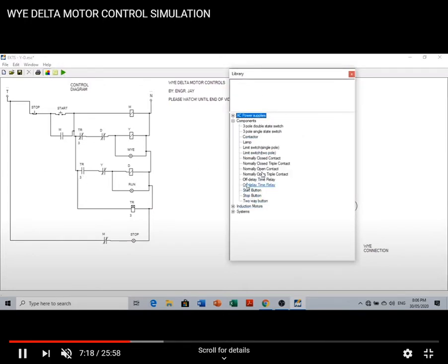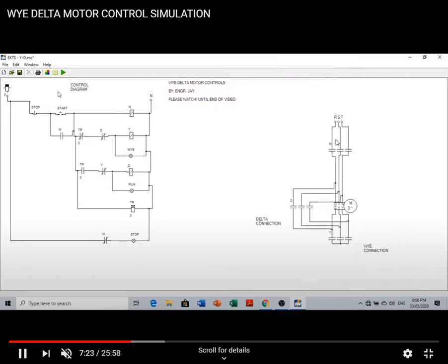What's another thing? We will put another off delay timer to create an automatic shutting off of the three-phase induction motor. So when we insert here, this is the off delay timer. We will insert this as well at an open contact of terminal T off.